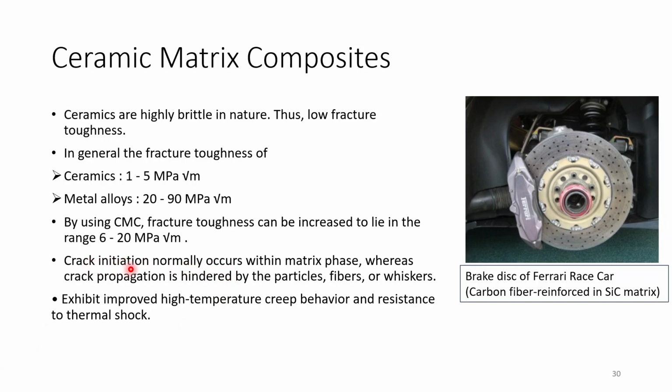Crack initiation normally occurs within the matrix phase, whereas crack propagation is hindered by the particles, fibers or whiskers, so they try to deflect the crack, leading to enhancement in impact strength. These exhibit improved high temperature creep behavior and resistance to thermal shock. This is the brake disc of a Ferrari race car, which is made of carbon fiber reinforced in a silicon carbide matrix.